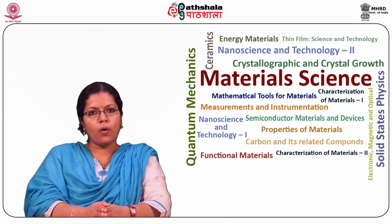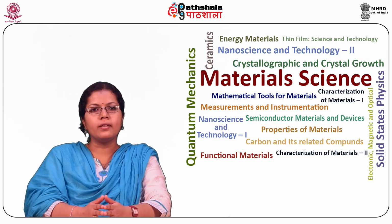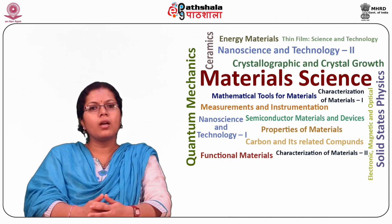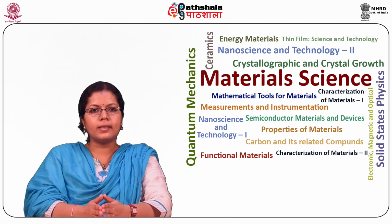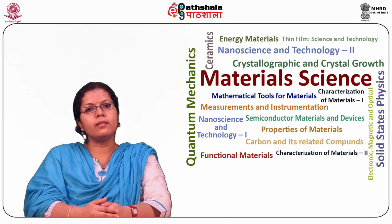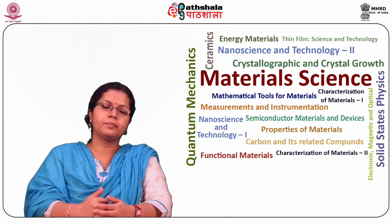Most voltmeter coils are wound on metal frames to provide the required electromagnetic damping. Most ammeter coils, however, are wound on non-magnetic formers because coil turns are effectively shorted by the ammeter shunt. The coil itself, therefore, provides electromagnetic damping.